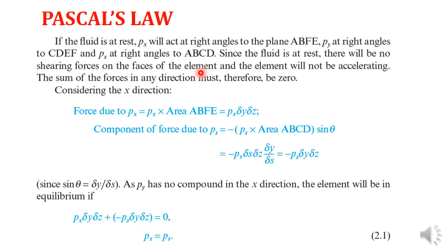That will be our first assumption, or the basic assumptions to derive Pascal's law: that your fluid will be at rest, no shearing forces are going to be developed within it, and the element will not be accelerating. So the sum of the forces in any direction must therefore be zero. The summation of the forces in all directions must be equal to zero.